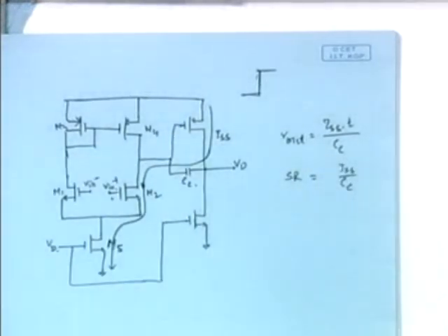So CC helps you determine that also. In the determination of slew rate, there is a portion of CC, so the compensation capacitor acts in two ways. One is phase margin, the stability of the op-amp comes with a good phase margin, which is given by the introduction of CC, the compensation capacitor, as we have already discussed.